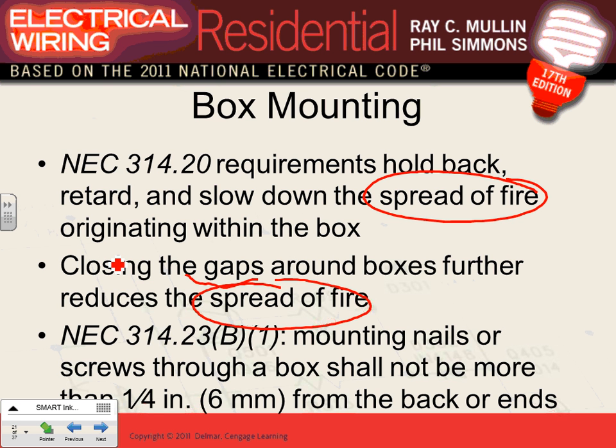If there's a fire up in the air, where is it going to spread? It's going to sit there and extinguish itself. So you put it in a building. That's why the NEC code book is mainly for indoor buildings. A lot of stuff is for indoor buildings. You go outdoor, they're so relaxed. I can run it right now on poles and tap from pole to pole with no box and keep moving, as I'm outside the building.